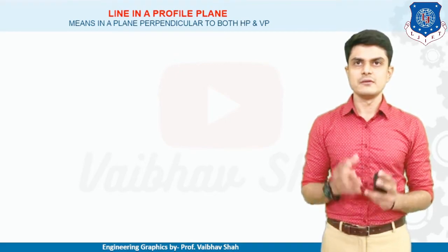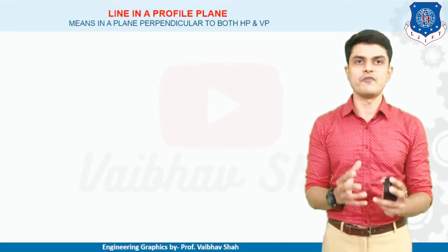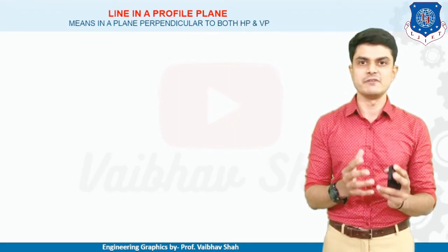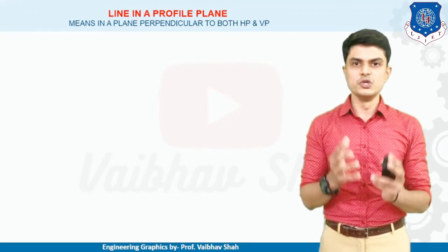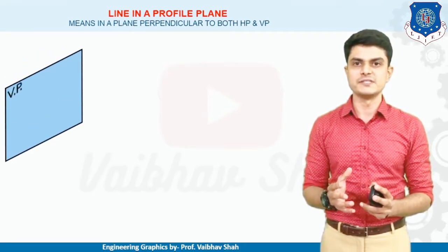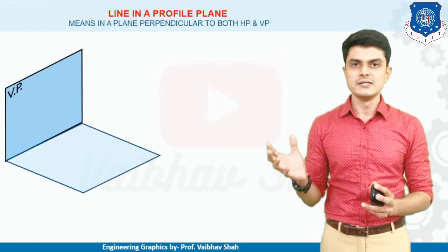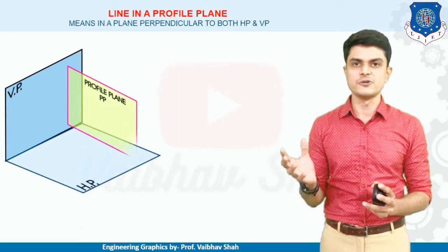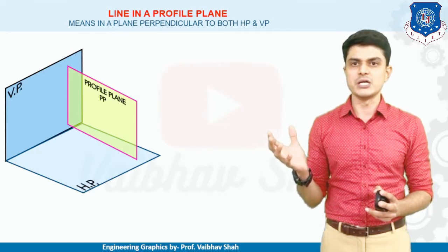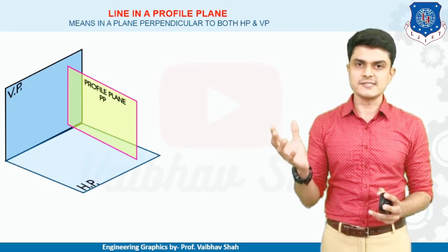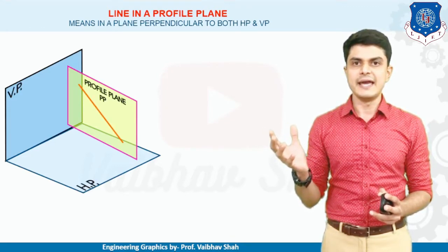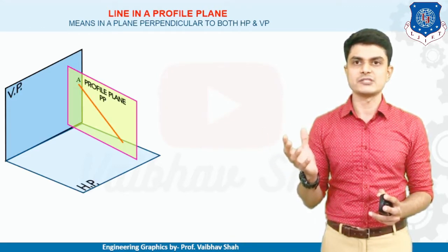Now the line is in the profile plane, meaning a plane perpendicular to both HP and VP. So we are introducing one new plane, which is known as a profile plane. Let us understand it by a pictorial representation. This is our vertical plane, this is our horizontal plane. Now we are introducing our third plane. As you can see, our third plane is perpendicular to both HP and VP. So this is nothing but our profile plane. Our line would now be in our profile plane, and thereafter we solve this example.